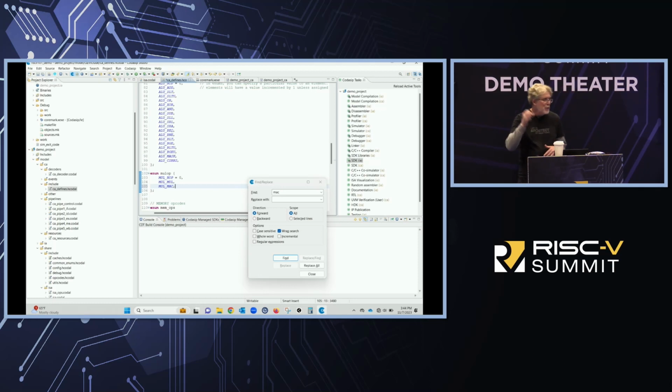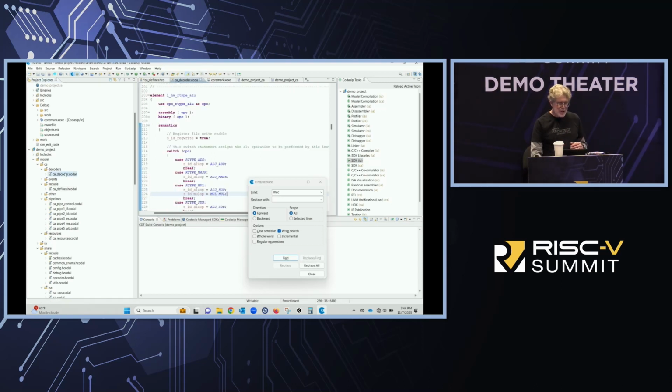Now, if you notice, I have 3 microcode opcodes now, which means I need at least 2 bits to define my microcode opcode. I don't have to go anywhere to change it because it will automatically bit size correctly to the number of bits that I have in my microcode. Now, let's go now to the next level. That's the first thing you do. So the next thing I have to do is I actually have to add that